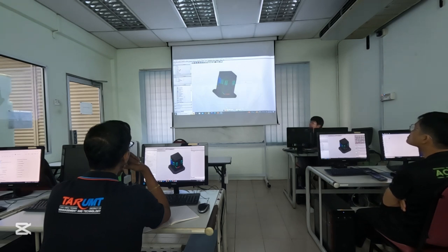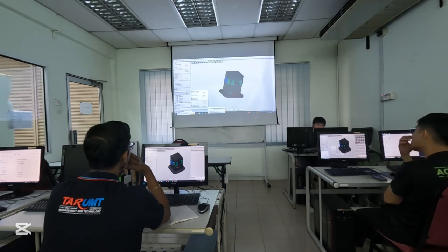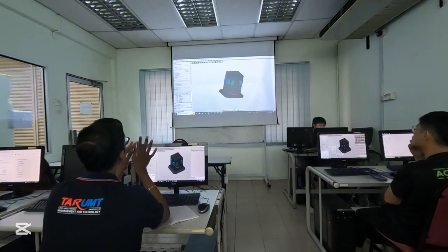So this is what I do with my Hyperview. After you set your preference, you can save it in File, Options, Layout Manager. You can save the current setting as a configuration. So next time when you open it back, if it's in default, if you already saved it, you can restore the configuration setting. Let's say I save first.